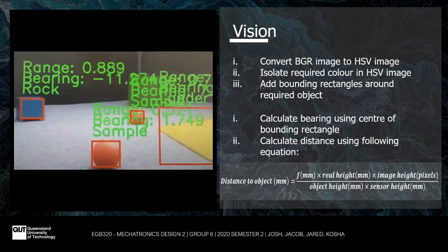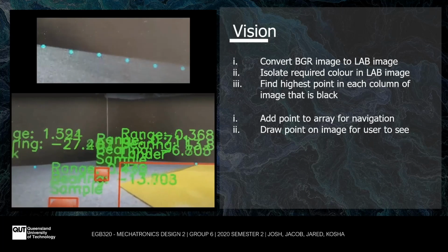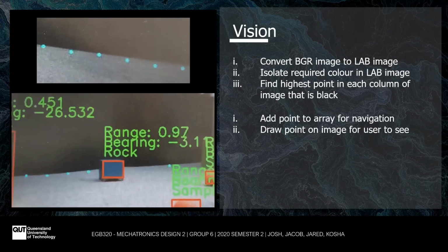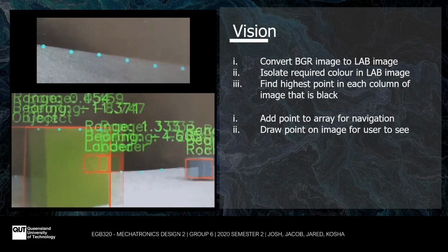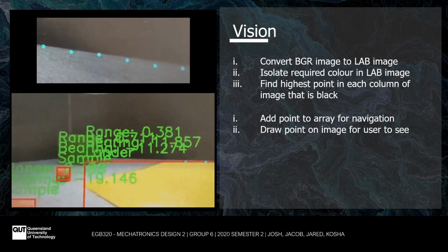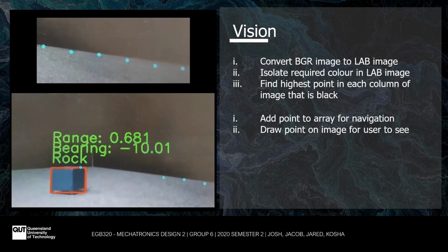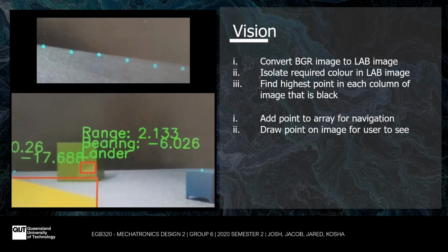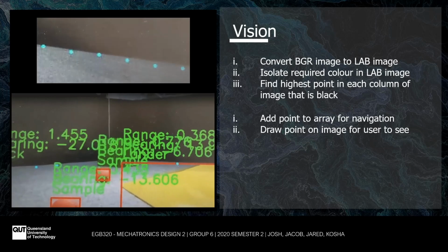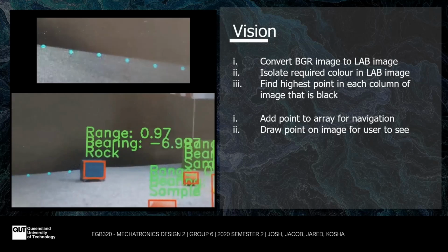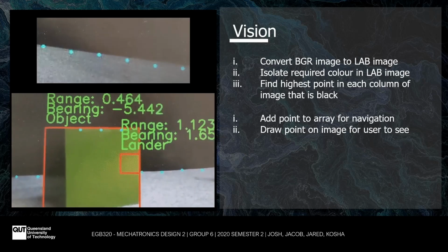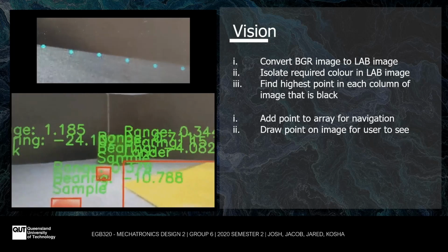The boundary of the arena is done similarly, with the image captured being converted into the LAB color space, so a mask of the wall can be created, from which the program determines where the wall touches the ground of the arena. The result is a pretty robust vision system, where all necessary objects within the arena are detected with very few false positives and almost no false negatives seen. The boundary vision also works quite well, following the outline of the arena, only having problems when an object obstructs its view, which is fine as the object closer to the robot is more important.